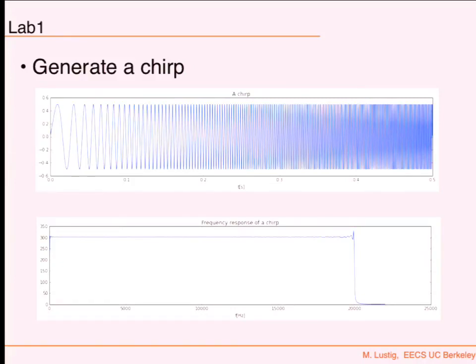If you think of me moving in time, it's also changing frequency in the same way. It's called a linear chirp. If you look at the spectrum of a chirp, it's constant. Why? Because if I look at all the frequencies across a certain time, it just went through all of them. So there's energy in all frequencies, an equal amount of them. So it's a really interesting signal.